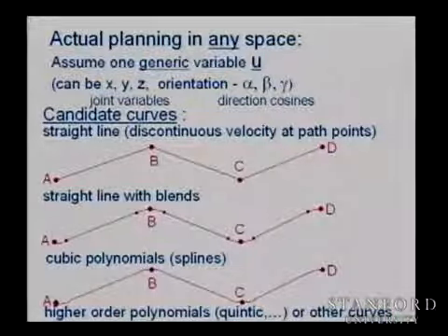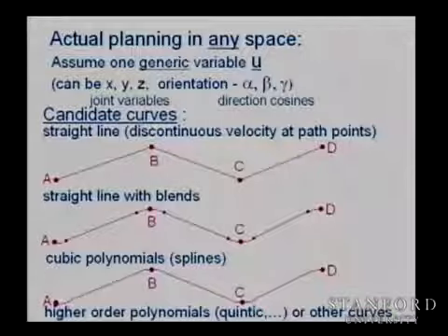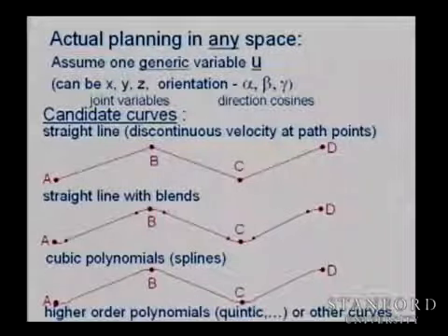Say you're starting from a certain position, you're ending at a certain position, you're starting with velocity 0, you're ending with some velocity, that's about it. If you want to control acceleration, deceleration, things like that, you need a higher degree polynomial because you need more coefficients to satisfy that motion. We'll see that in more detail. But of course, the higher degree polynomials you use, the more complicated the formulas get. Usually we try to get away with the simplest thing we can. Okay, so far?